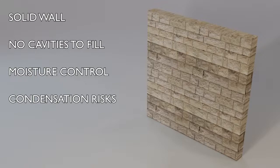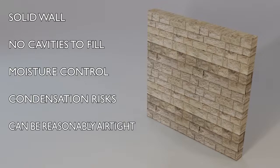Although a lot of existing solid masonry walls offer very limited thermal insulation, the traditional plastered or hard finish can be reasonably airtight if kept in good repair. On the other hand, traditional plasters and mortars can be very sensitive to changes in moisture levels. Depending on the nature of the thermal upgrade, vapor-permeable air barriers like our Airtight can be a good fit in this type of construction, as they can restrict the passage of air without having a substantial effect on the existing moisture balance.